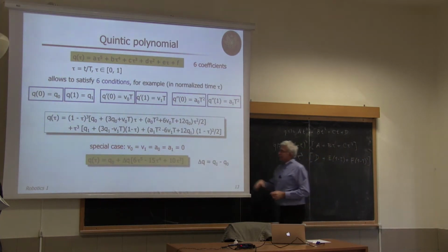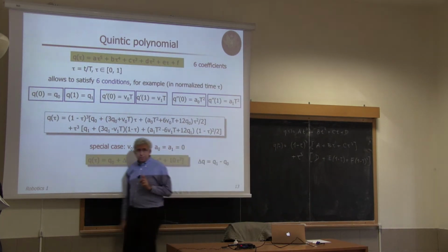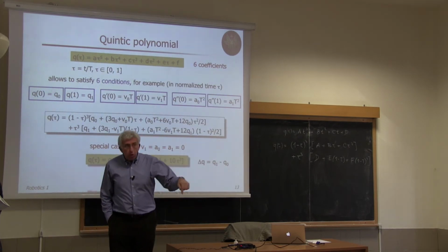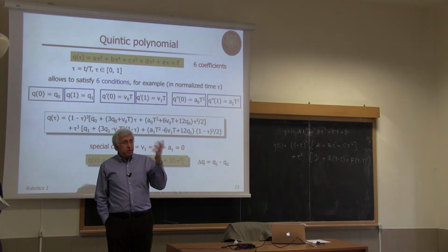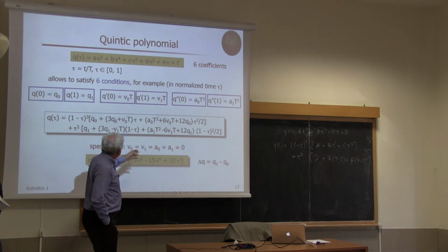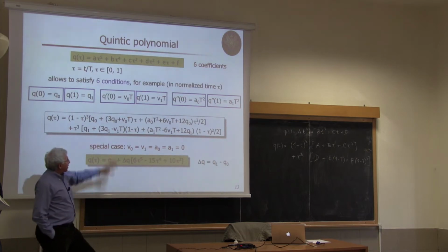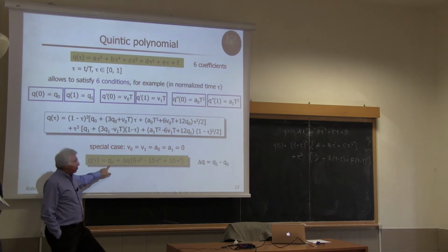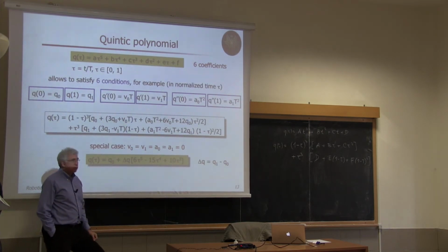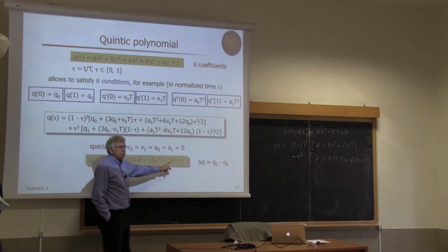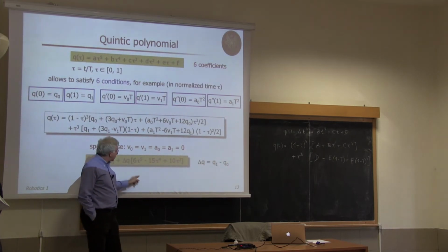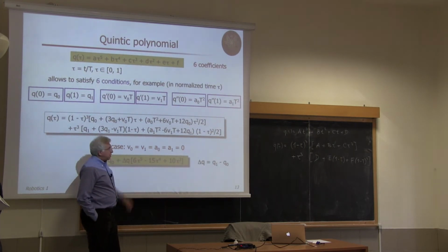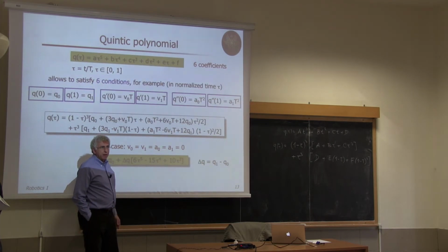Now again, look at this. If you impose a rest-to-rest motion, so you start with zero velocity and end with zero velocity and also with zero initial and final acceleration, okay, so you put zeros to this. Then you can reorganize things exactly in this double normalized form where you start from q0, delta q is the variation q1 minus q0, and here you have the doubly normalized polynomial with tau going from 0 to 1 and in time, let's say, and with this polynomial moving from 0 to 1 at the end point.